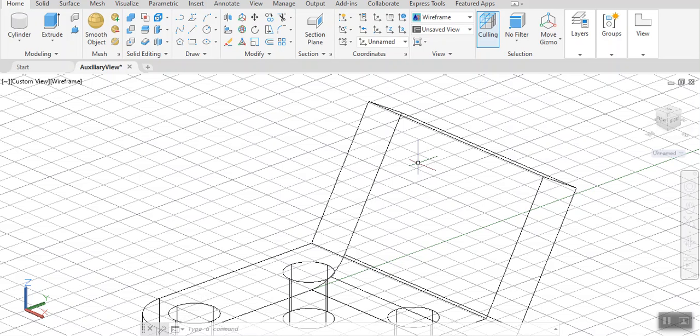Whenever there is, please remember this one, this is very important, it's right in the stone: whenever there is an inclined surface at an angle other than 90 degrees, orthographic views come short of depicting the 3D solid object. For the reason being, orthographic views only give you 90-degree angled surfaces. Any surface other than 90 degrees will be distorted. This is called angular distortion. Because it is distorted, it cannot be measured directly on an orthographic view drawing.